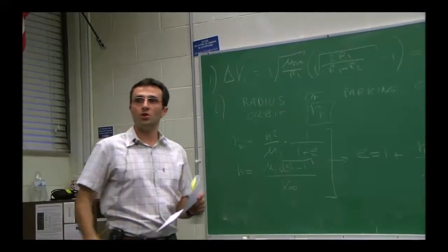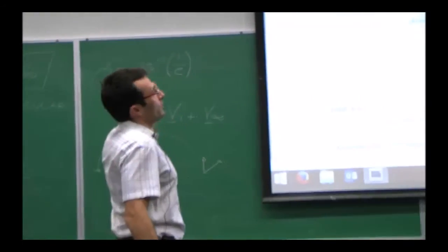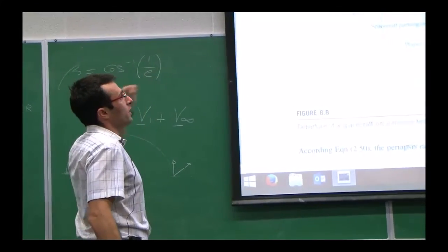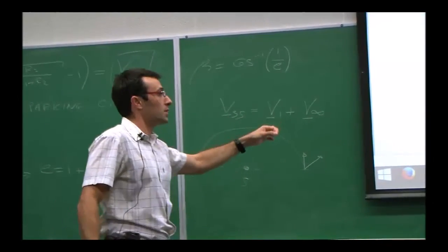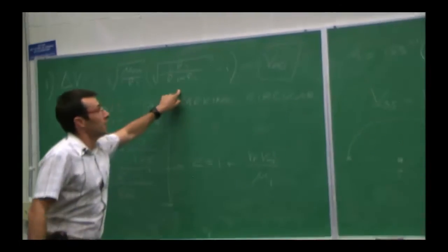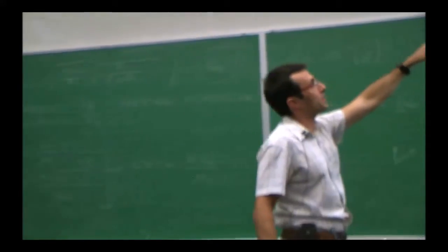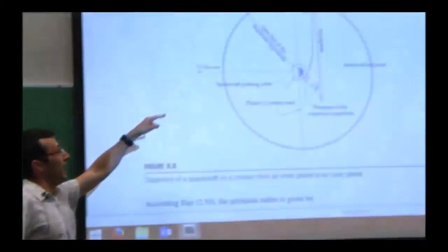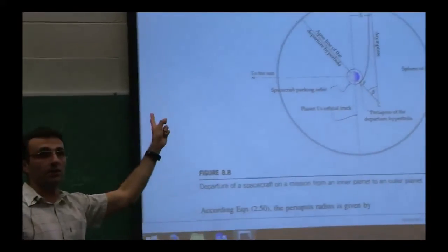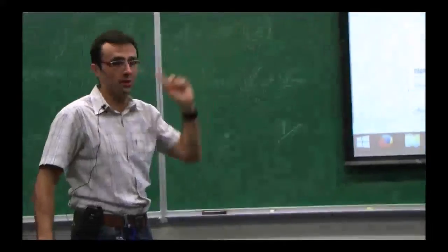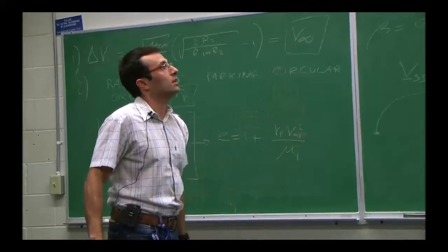Make sense? So basically the idea of the patched conics is, from the sun's perspective, you know the velocities you need to have as you leave a planet and you arrive on the other planet. Once you're given those conditions right here, you call those v infinities, and then you enter the sphere of influence and you make sure that those v infinities are met and they are as vectors pointing in the right direction. And again, if you do Hohmann, you just want to be with the velocity of the planets. No angles between those.